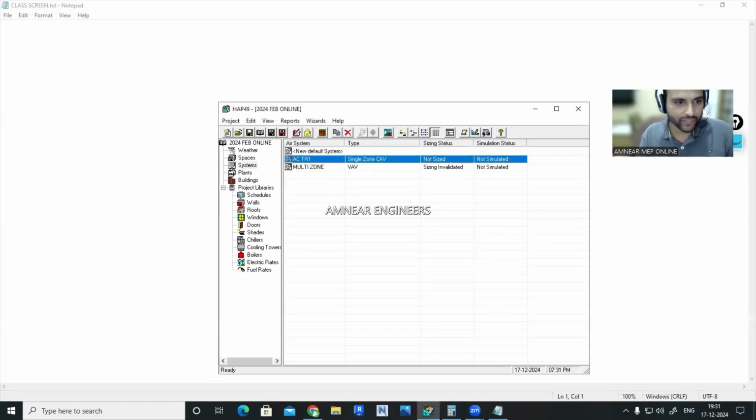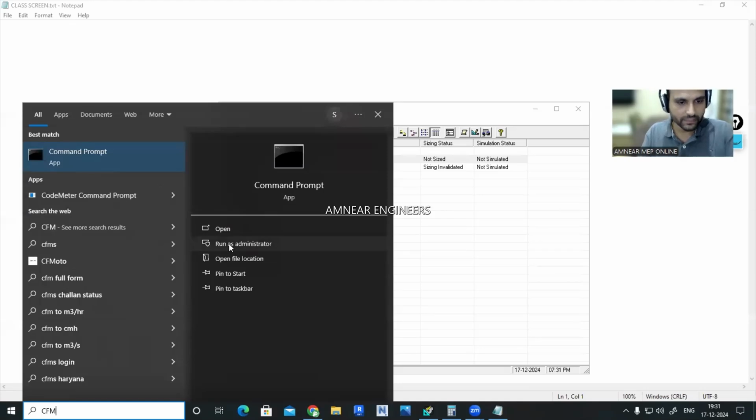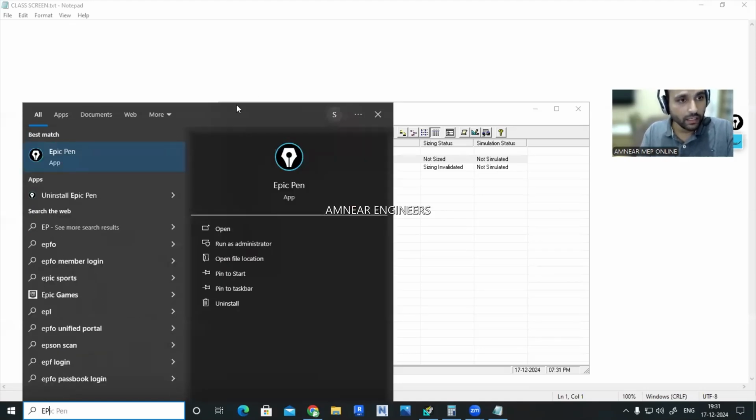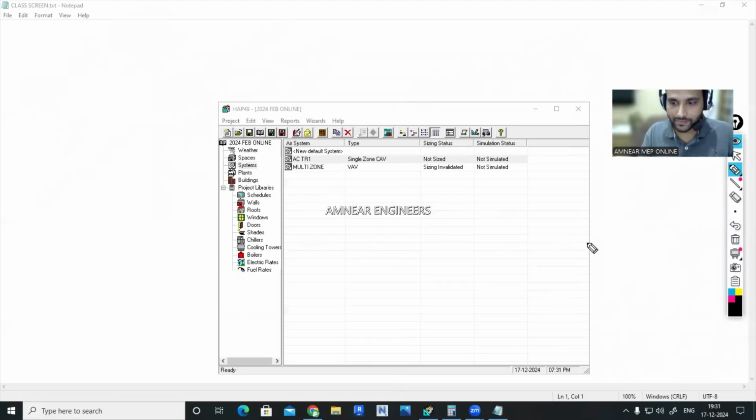And what will happen if we are not getting the required CFM? For example, after the heating and cooling load calculation, we will be selecting the machine. When we go to machine selection, the ton of refrigeration, airflow rate value, everything will be there. So normally plus or minus 10% fluctuation from the design value is permissible. Even if sometimes you're not getting any option in the market, up to 20% is also, let's say, you can close your eyes for the time being. But normally plus or minus 10 to 15% fluctuation from the design value is permissible.